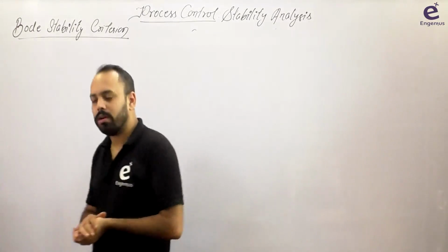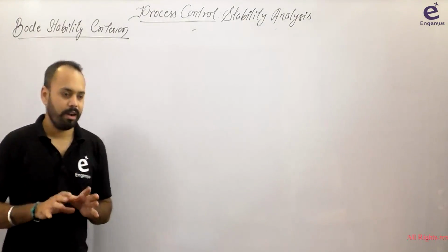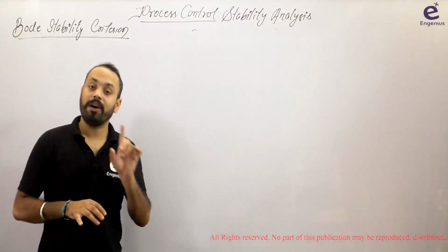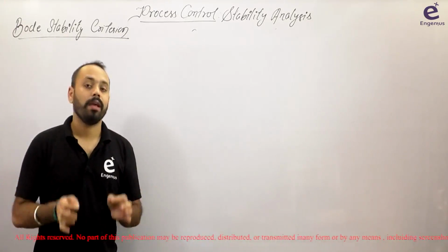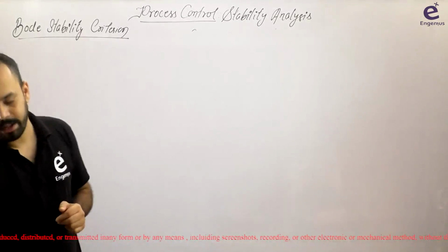So that point you must remember: in Bode stability criteria, first of all you have to think whether there is a crossover frequency or not, a finite crossover frequency or not. If no, always stable. If yes, apply the Bode stability criteria. Now what is Bode stability criteria? Let's see.